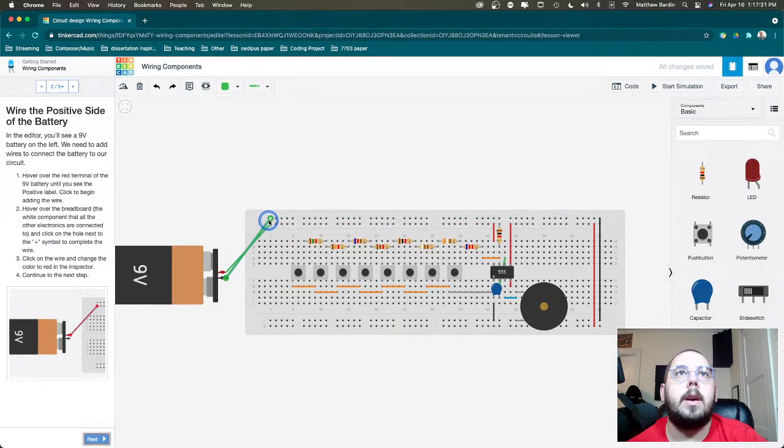If you wanted to, you could drop it down here as long as it's on that negative kind of row. Everything will line up. You'll notice that, again, like all breadboards, the one side does not link up to the other, but they've gone ahead and in this example set up these jumper cables to patch that up, so both sides will line up.